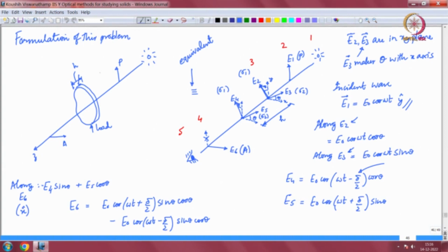And once the polarized light passes through this, of course, because the optical axis is oriented in the direction of one of the principal stresses, the refractive index in that direction is different from the refractive index in a perpendicular direction. So, the two waves essentially split, the two polarizations split, and they travel at different speeds, and then they recombine once the light exits the material, and then there is some phase lag delta, and we basically probe this phase lag by using another polarizer which we call the analyzer, or A, that is placed perpendicular to the initial sheet. Okay.